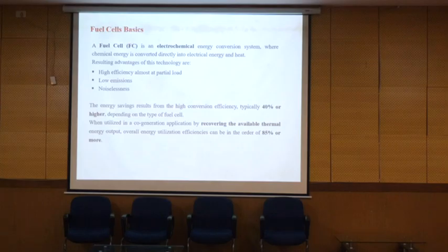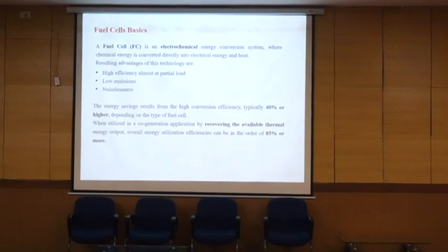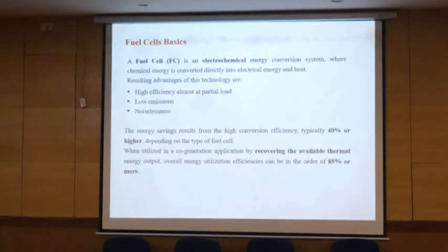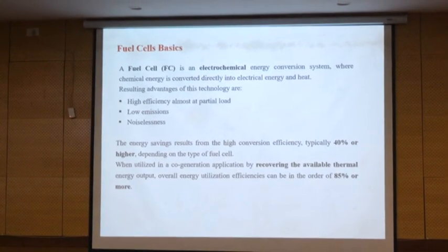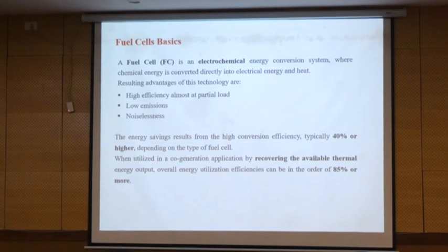If you are going to allocate green hydrogen in a future system, in a modern network where fewer synchronous generators are working and we lack enough inertia, then the system will be more dynamic. If something happens, the fuel cell is not fast enough to compensate or support the dynamic stability of the network.